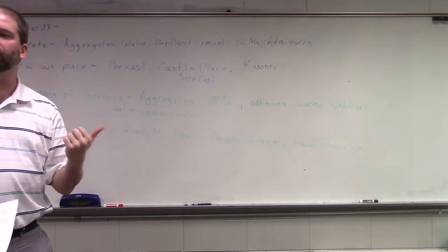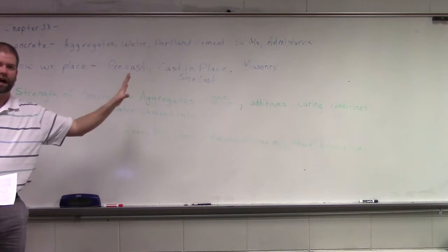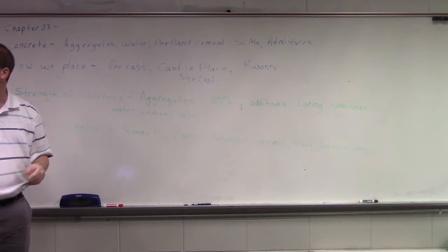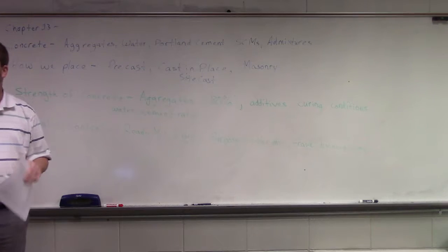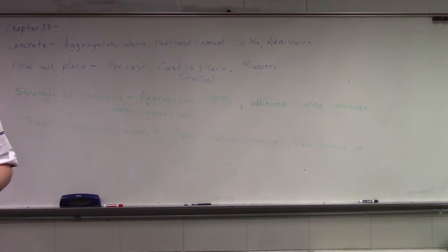We don't really need to worry about it here in the Midwest, but once you get out to the Rockies and beyond, they have elevated rates of sulfates in their soil. So they need to make sure that it's not reacting with the cement chemistry causing expansion. And then we also have high early, where they take the cement and grind it a little bit finer. So those smaller particles take up water faster, it hydrates faster, and it also typically generates a little bit more heat. But the high early and the general use are what they talked about.